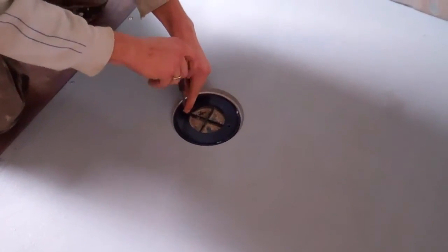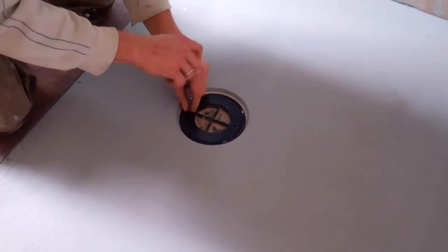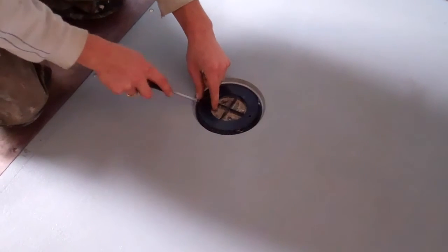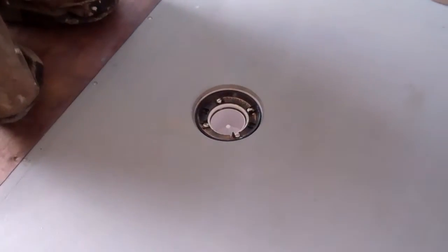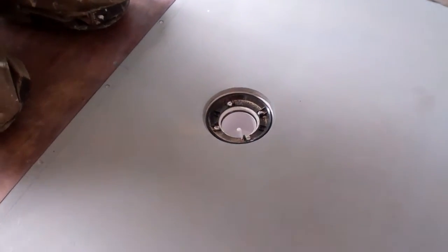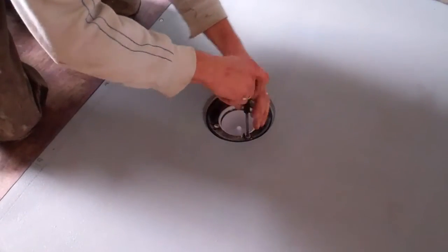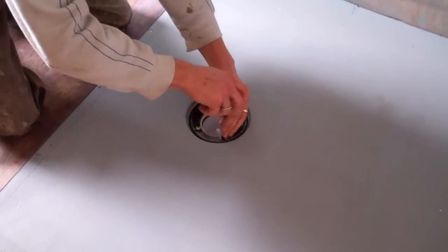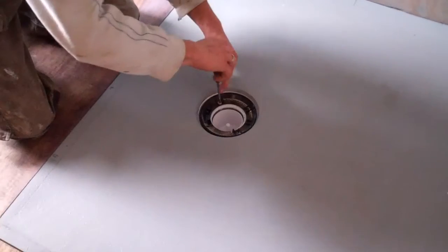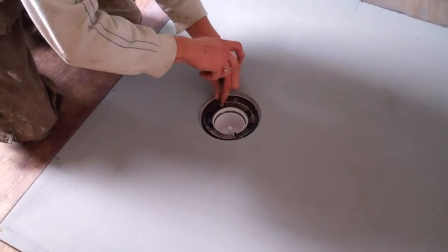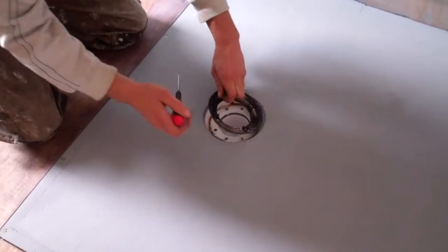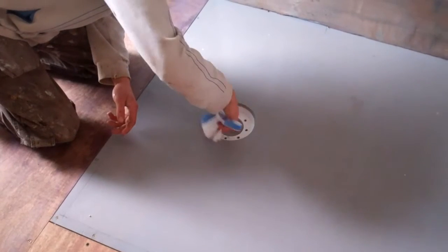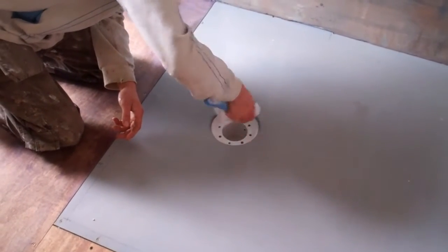Next we are going to install the large sleeve into the drainage gully. Start off by unscrewing the 2 retaining bolts and removing the dust cover. There are a further 4 retaining bolts securing the clamping ring. Remove these and remove the clamping ring. Brush off any sawdust or other foreign material that could potentially damage the sleeve.